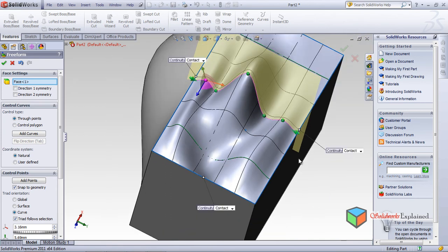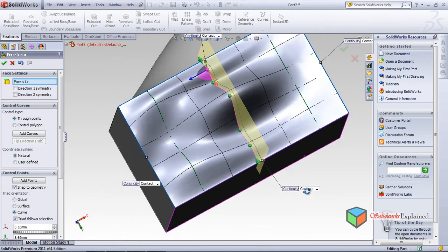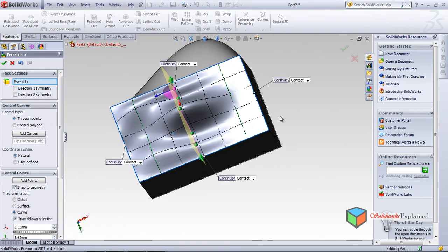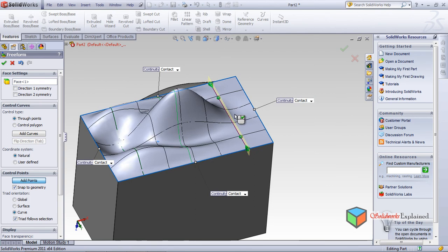And where is my third line? I haven't added any points in the third line, but why wait? This is my third line, and I will add some points on it, only 2 points, one here and one here. That's alright. And then after adding 2 points, I don't want more points. So here one more click is necessary, otherwise it will make a line.